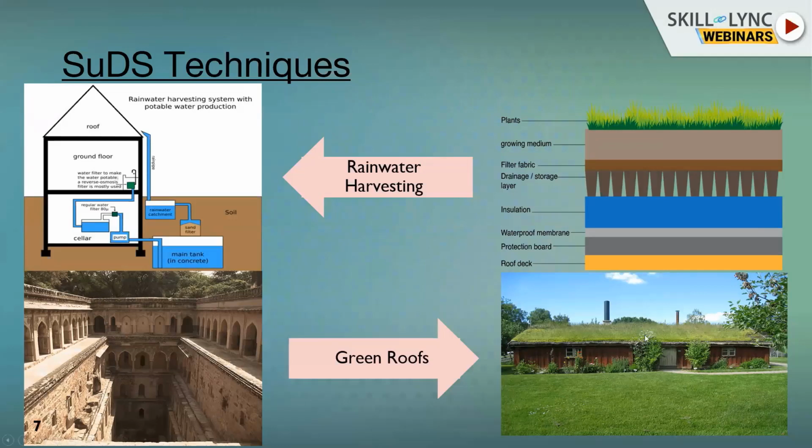In addition to these green roofs, there is also a blue roof. The only difference in that blue roof is these plants are not provided, and in place of these growing mediums, there are gravels that are provided. So they provide a void space and water stands there. So basically, it is more of a storage structure than one for evaporation or evapotranspiration.